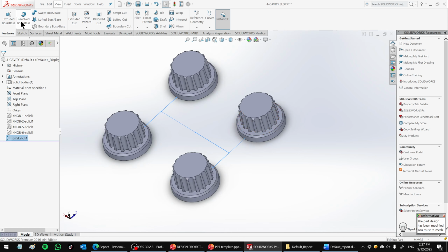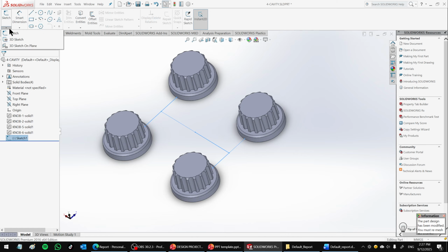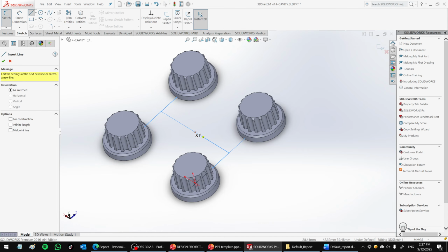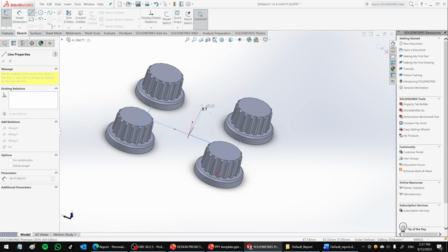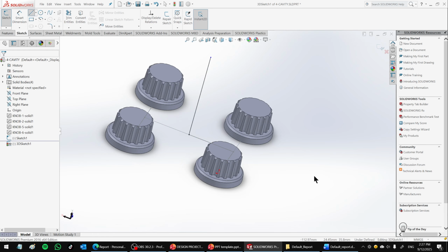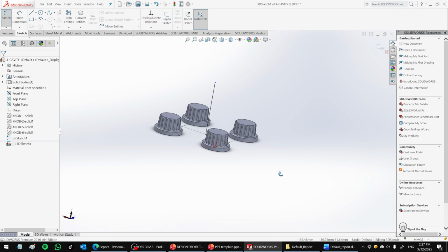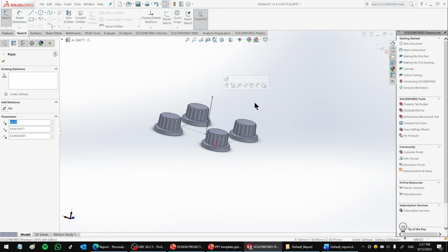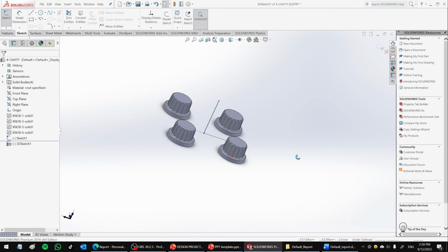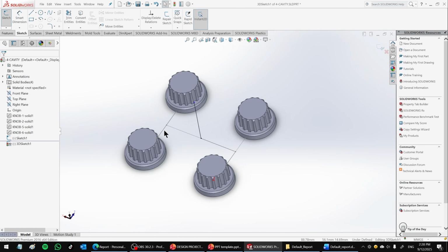Finally, you need to do another 3D sketch. Go to sketch, click here, click 3D sketch. Go to line, go to the center here. And then you want to do the sprue. The sprue is probably that length. Too long? Shorten it a bit. So that is the sprue. So every single line must be connected, but each with their own section. So now I can exit.